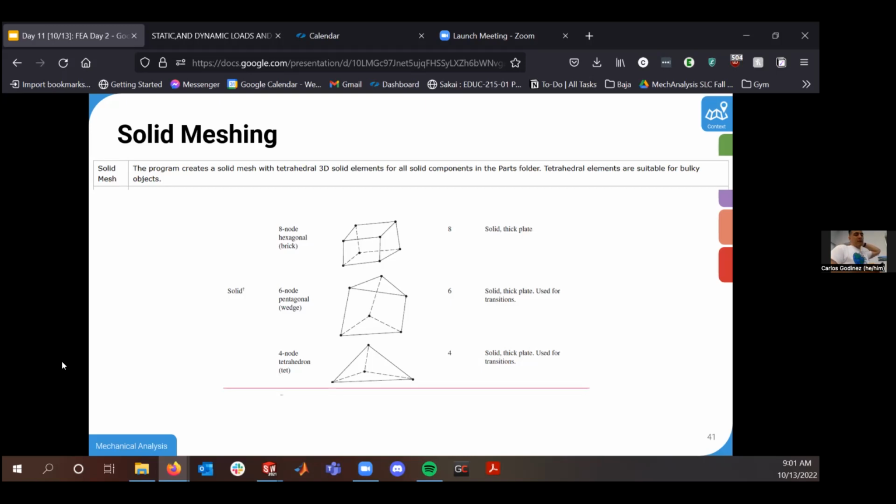Solid elements, and if you remember from last week, we have usually first or second degree elements. First degree only has nodes on the vertices of the entire element. This is great for real quick, fast, and dirty FEA, but it also has some distinct disadvantages.